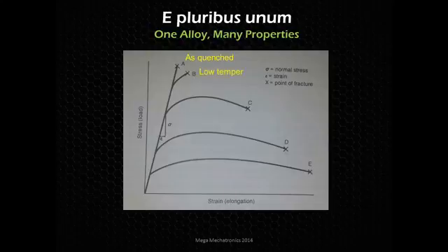You need to temper it, any temper. So let's say we do a low temper where it's at a lower temperature or shorter time or a combination of both. Here's maybe a higher temper where you are bringing it up to a higher temperature and you're leaving it there for longer. And here's possibly a normalized material, and then a full anneal where you're resetting it, and you can see the wide range. So anything in between A to E, you can give that property to that material, and that all depends on your application.